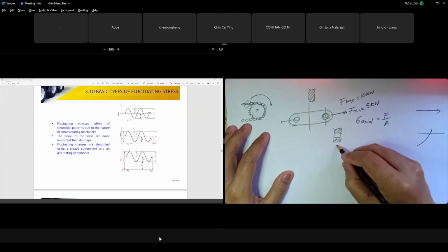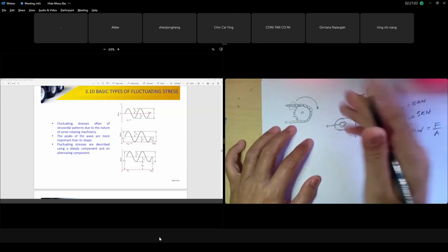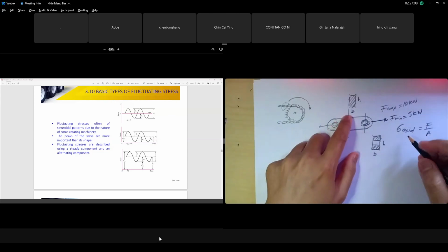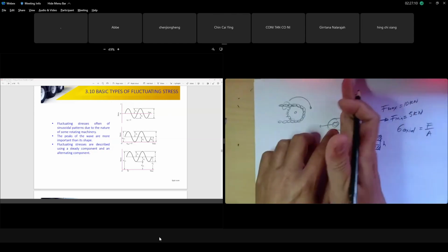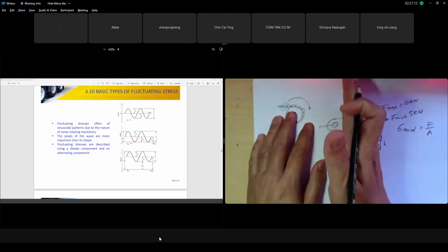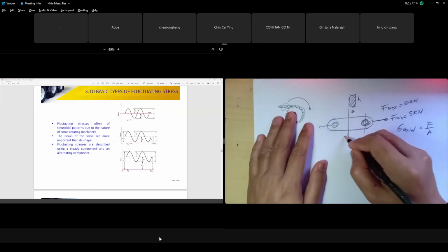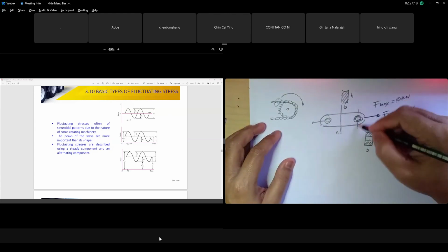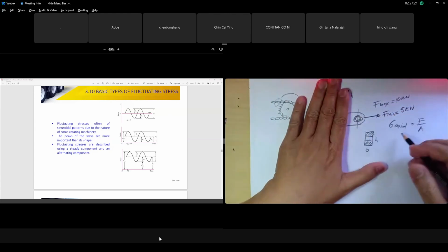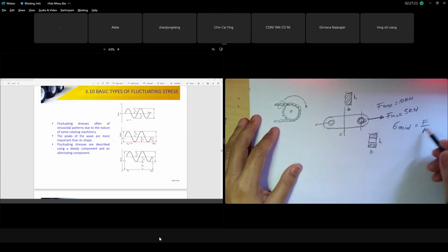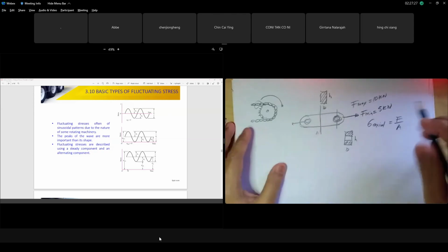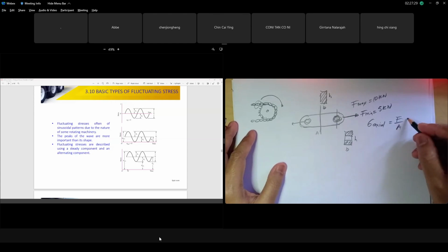Over area. So this is your BH. So you can use the area that you deduct, if your focus is at the center, not at the holes here. This is your BH, you know, area is BH. Let's say you focus at the center, fatigue analysis at the center, at A section. Actually the weakest is here, in engineering you focus on the weakest. So my point is, sigma axial is F over area. Area where there are no holes is BH.